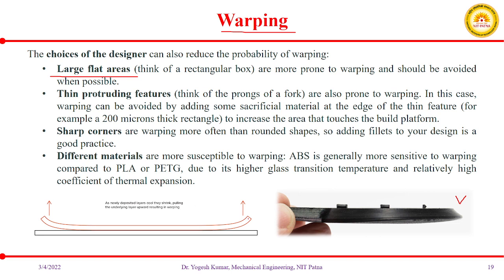Let us continue first. Sharp corners warp more often than rounded shapes, so adding fillets to your design is a good practice. Fillets need to be added to sharp corners.